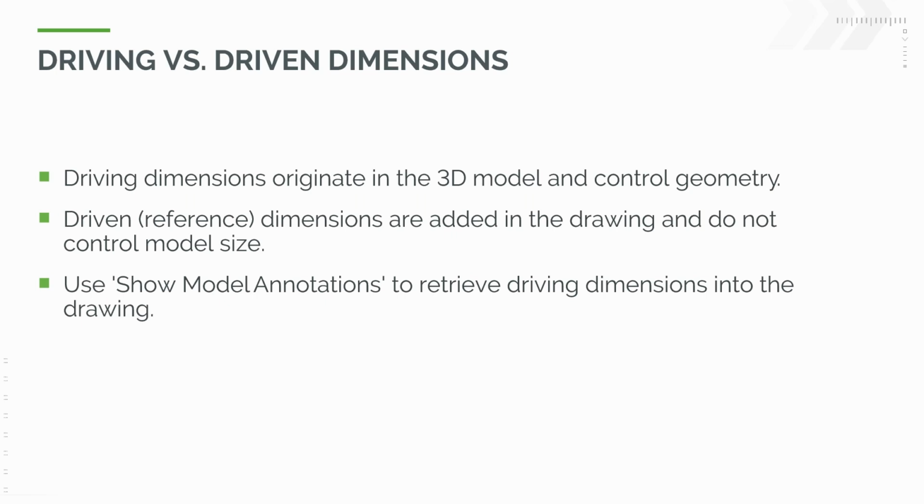So related to this very closely is the show model annotations function inside the drawing environment, which can allow us to quickly and easily show driving dimensions, so the dimensions from the model, into the drawing. Okay, so I'll have a look at that in a sec.